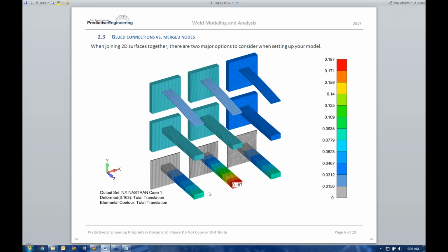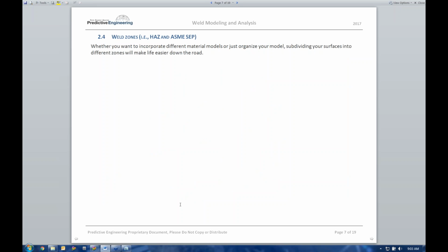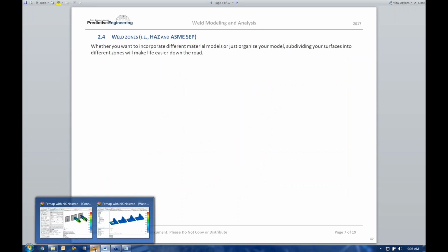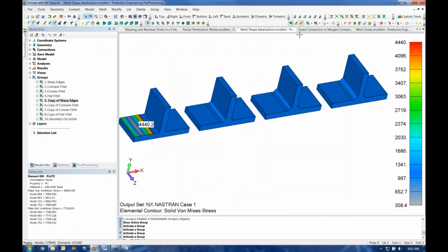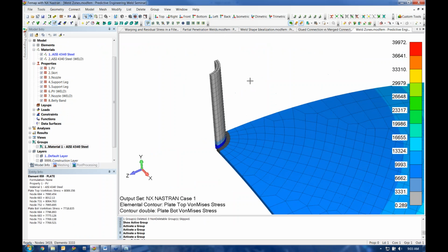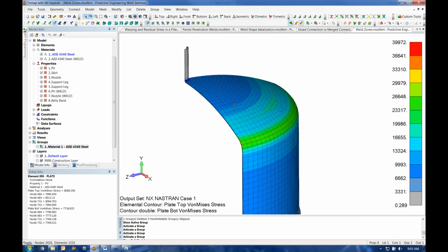All right, I've got one more meshing example here, and that is for the fillet welds. Let's go back to our pressure vessel example. Now, when I pass on to Kyle, he's going to describe how to extract some of the forces from your model, and rather than focusing on the stresses for a fatigue analysis, let's say the first step is simply sizing the welds. How big of a weld do I need on my part? Well, you would model up the different components, you would extract the forces from those components, and then you can use hand calculations to give you a rough idea of what sort of weld size you're going to want there.